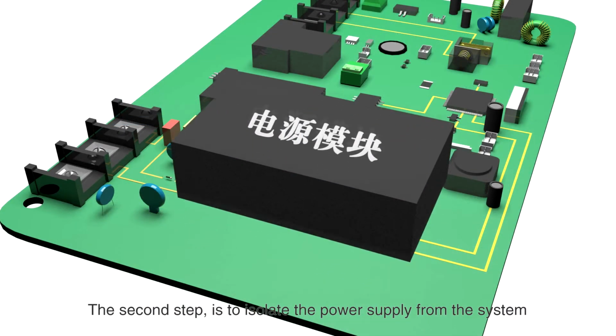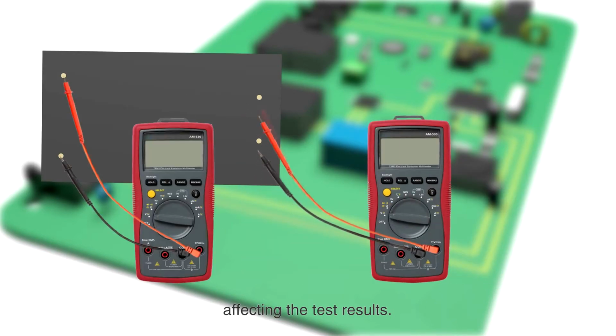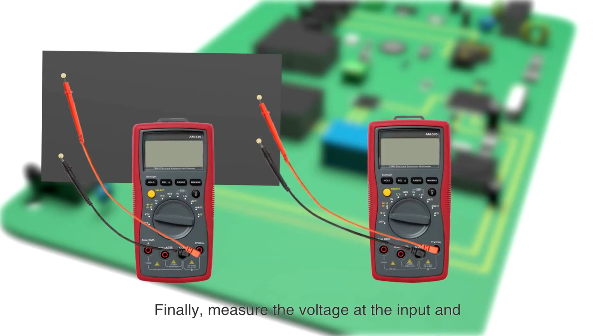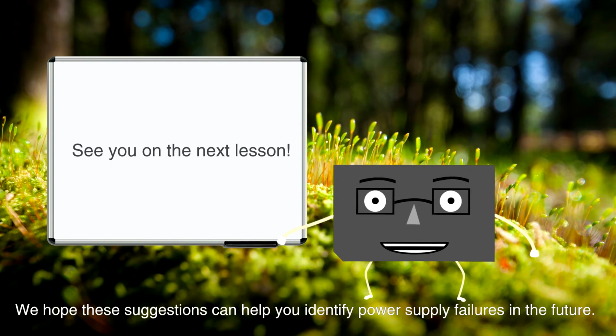The second step is to isolate the power supply from the system and test the power supply by itself to prevent outside circuits from affecting the test results. Finally, measure the voltage at the input and output terminals to get the most accurate data. We hope these suggestions can help you identify power supply failures in the future.